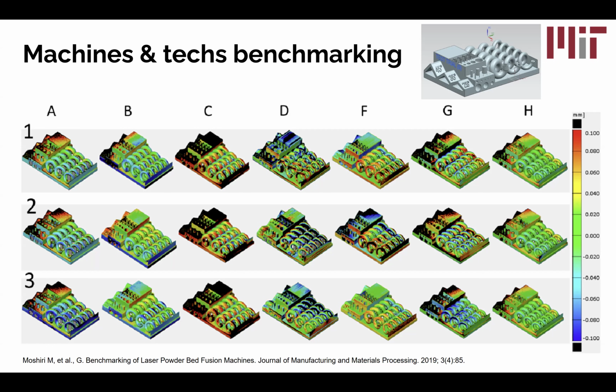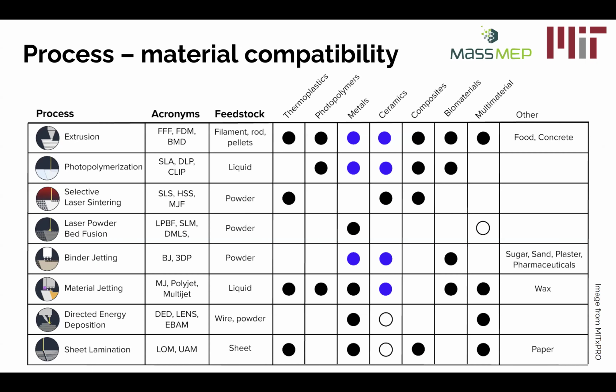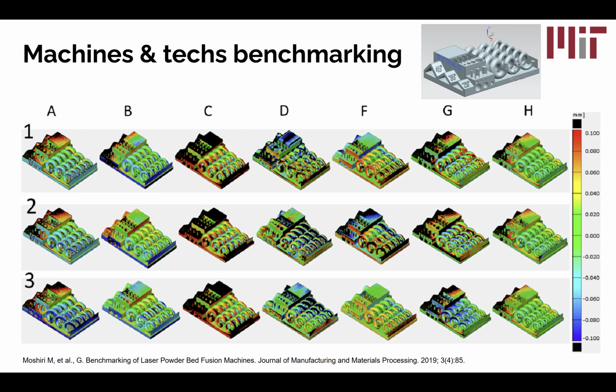And there are features like overhangs, small holes, thin walls, everything that you can find on a mold design, on a mold part. This specific benchmark was not done to compare different processes. The process that was meant to be used for molding was very clear: metal laser powder bed fusion. This specific benchmark was designed to resemble an application and to compare different suppliers.